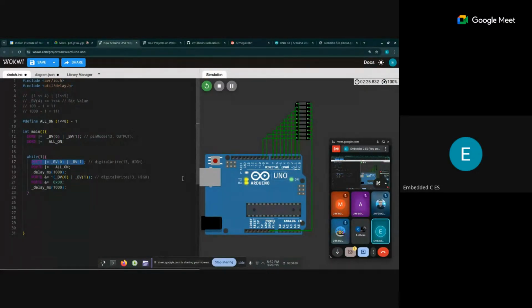So this is what is below the Arduino layer of code that you write. Whatever you write in the setup function will be called around this place, and the loop function will be called around this place. That's how generally this works. This is just like C code. Every Arduino code that you write finally gets translated into something like this.